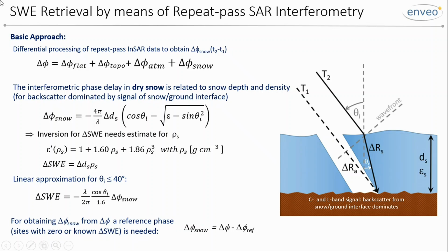We are measuring the interferometric phase, okay? Then we have a contribution of the phase due to the flat Earth. That is because the radar is going like this, but without topography. Then I have a DEM. This is the topo contribution, because we have height changes also in range. If I have a DEM, I can calculate both accurately enough.